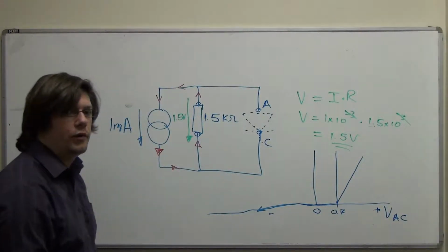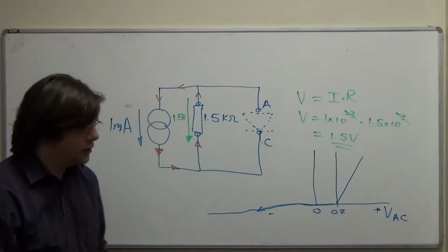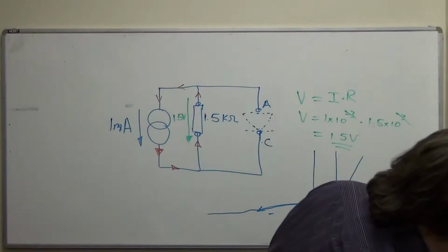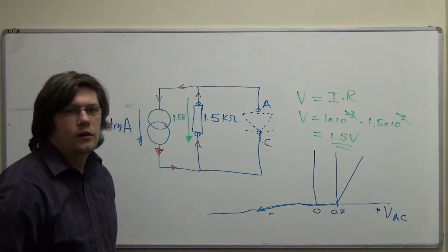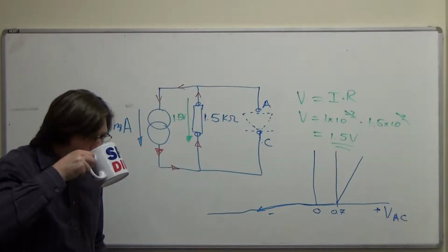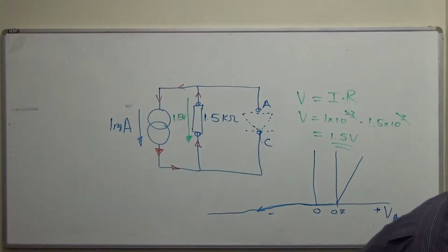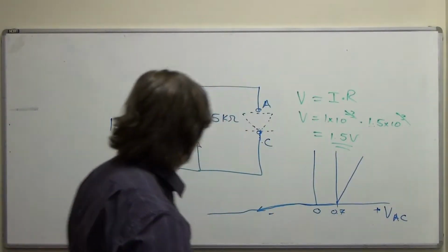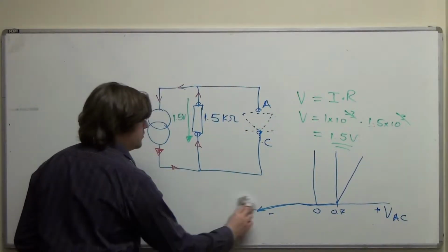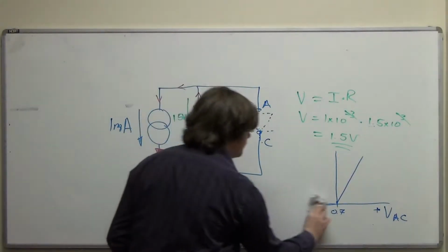It will never ever break down. Of course, in the lectures that we've been going through, I talked about impact ionisation briefly, and I said how the diode will eventually break down. But for the purposes of these questions, it's not necessary to worry about it, and we can just say it's reverse biased, there is no current, not even a saturation current.